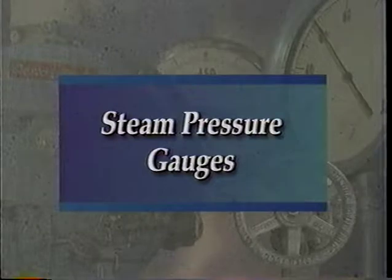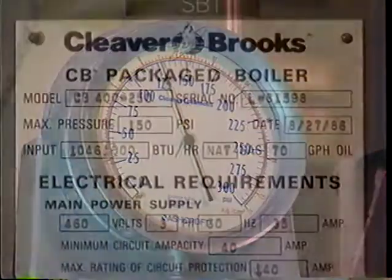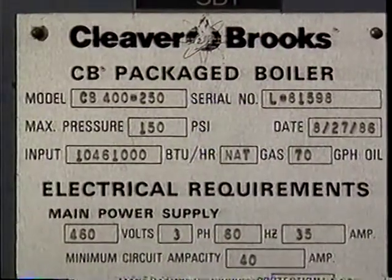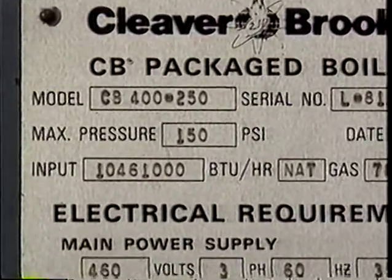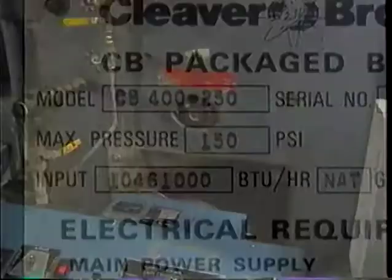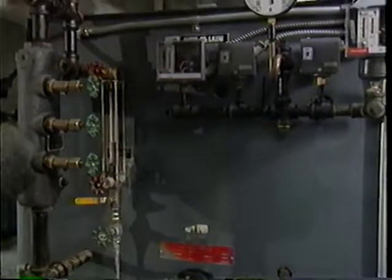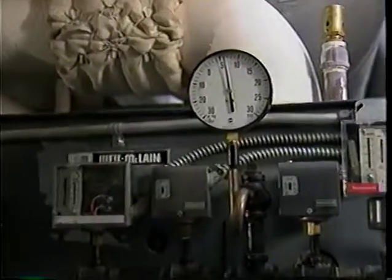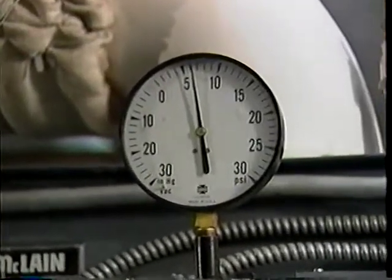Steam pressure gauges. Steam pressure gauges and vacuum gauges monitor pressure inside the boiler. The range of these gauges should be 1.5 to 2 times the MAWP of the boiler. For example, on a low-pressure boiler, a maximum steam pressure on the pressure gauge reads 30 psi as the MAWP is 15 psi.